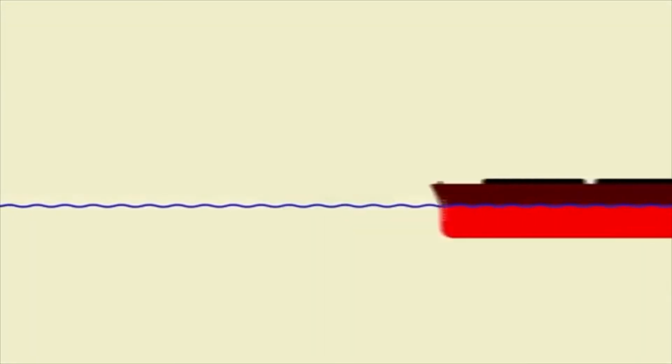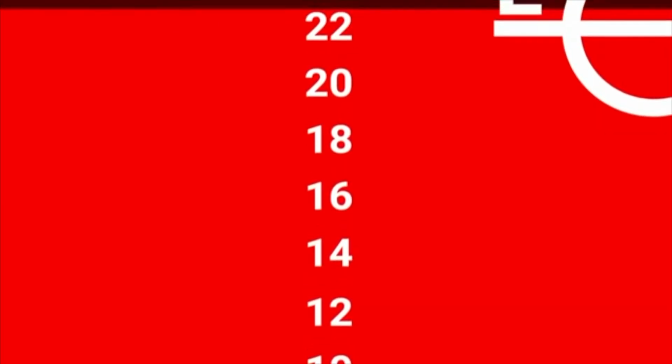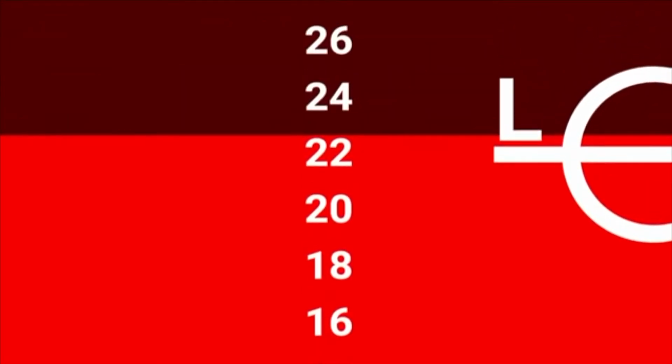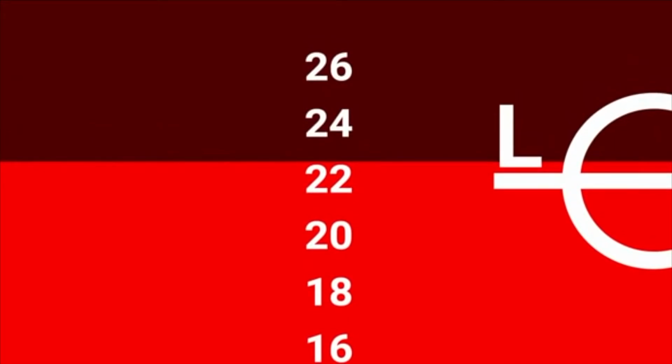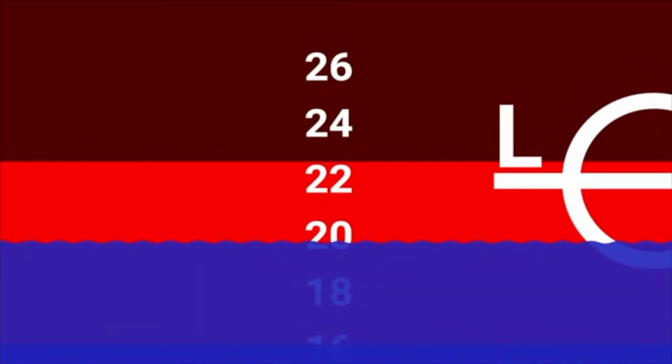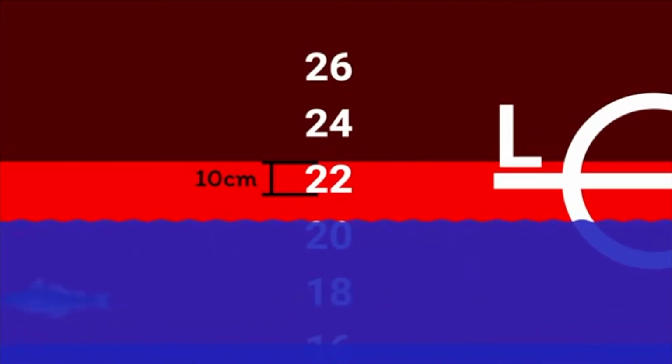For metric draft marks, you'll notice they sometimes give whole meters, and then they seem to count up in 20 centimetre increments. Others give decimeters instead. Of course, 20 decimeters is 2 meters, 30 decimeters is 3 meters, and so on. Again, these go up in 2 decimeter increments, effectively measuring every 20 centimeters. But if you look a little deeper, they're actually counting in 10 centimeter increments, and that's due to the height of the digits. When the water is at the bottom of the number itself gives the draft. When it reaches the top of the number, it's halfway up to the next digit.